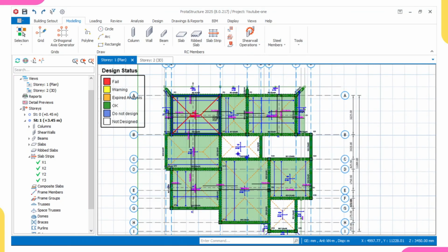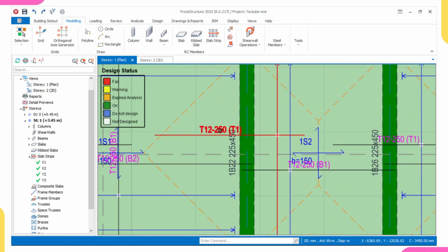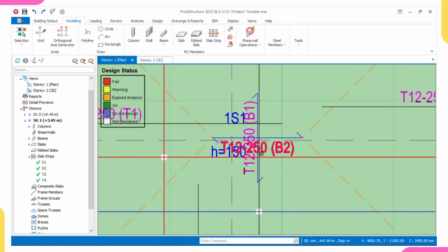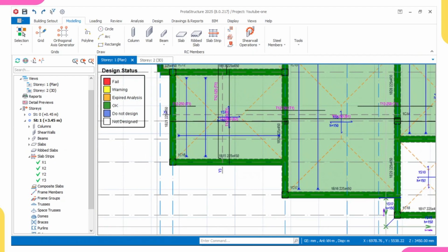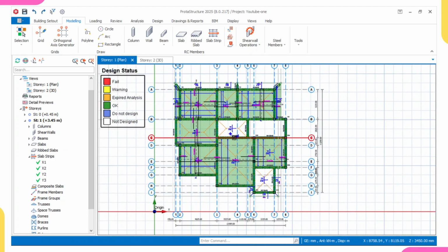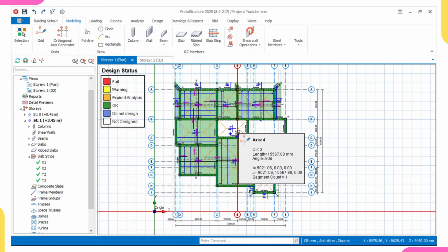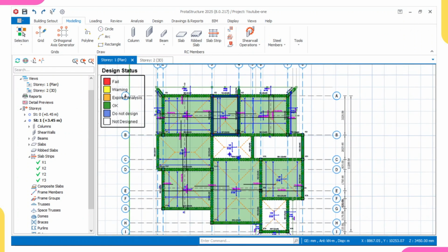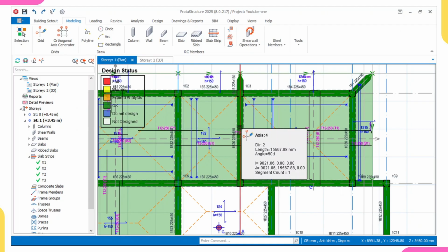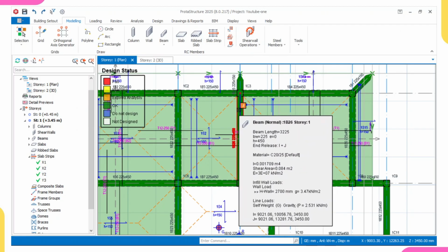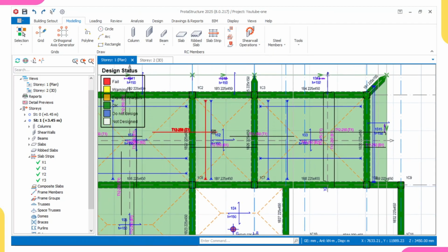In your own, you do it accurately. But me, if you look at everything here, I'm having Y12 at 250 spacing everywhere. So in my own detailing, what I use is Y12 at 200 spacing. The reason is still what I told you concerning beams. I'll use Y12 at 200 spacing because most African countries, even where I'm located, which is Nigeria, most of our companies tamper with quality.